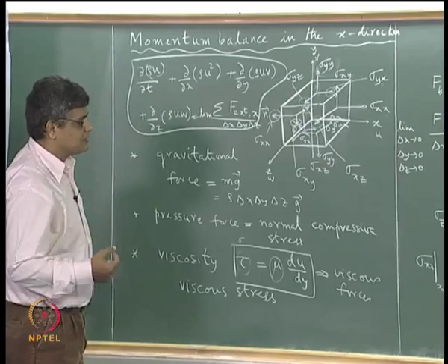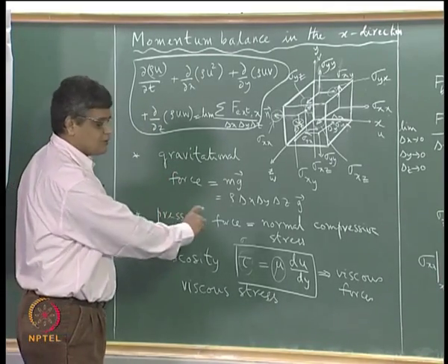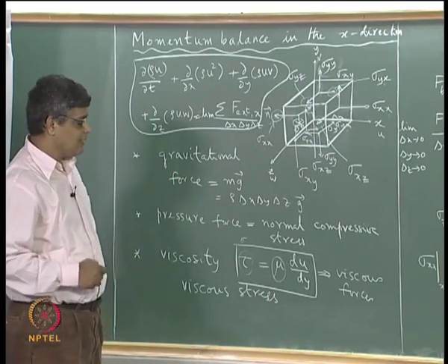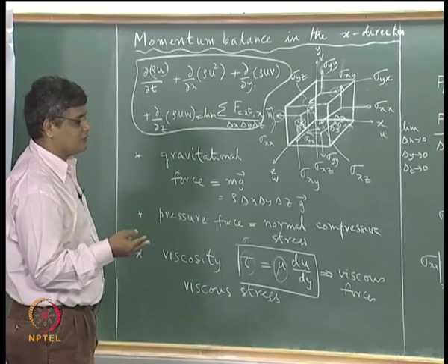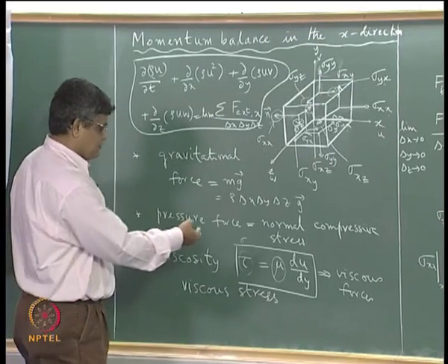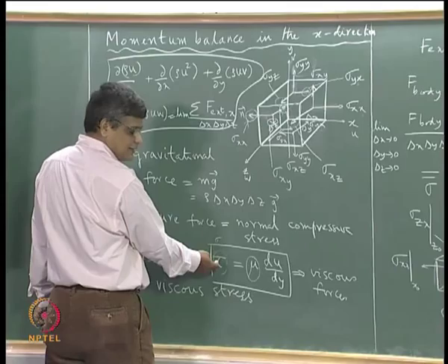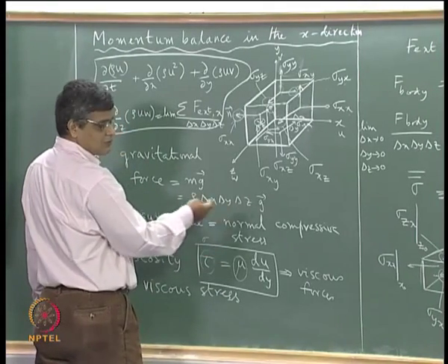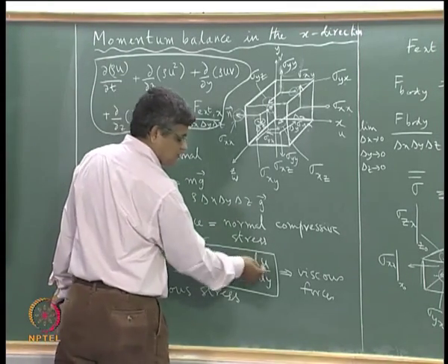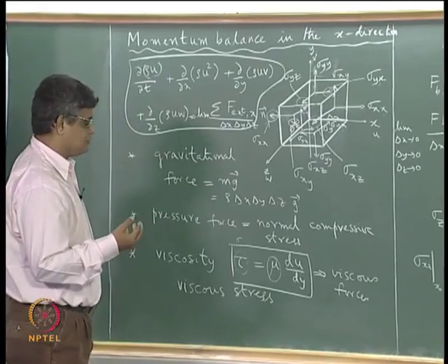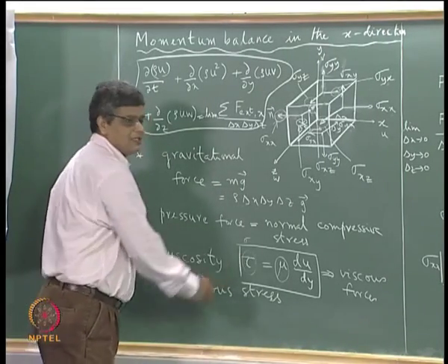Okay, so we need to describe the stresses in terms of known quantities, and this is a kind of constitutive equation which, for example, here says that the shear stress induced by relative motion within the fluid is proportional to the strain rate. So that is a constitutive law which is being described mathematically here.